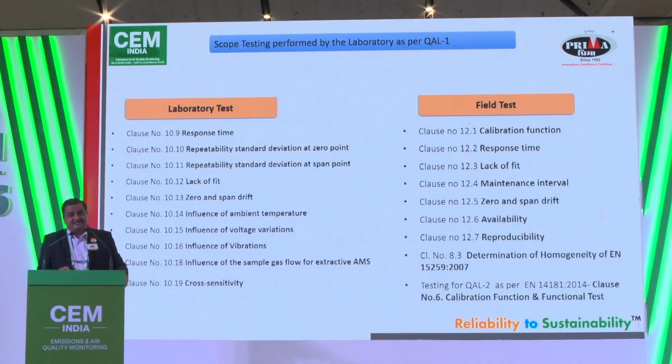So these are the parameters of the laboratory test. When you buy a certified equipment, ask your supplier to provide a test report of the ISO IEC 17025 accredited laboratory for all these parameters of the clauses, along with that certificate. That will make a difference, and you will have confidence about your product and your data output. Don't use your CMS only for compliance. Use it for your process optimization, and that is most important.